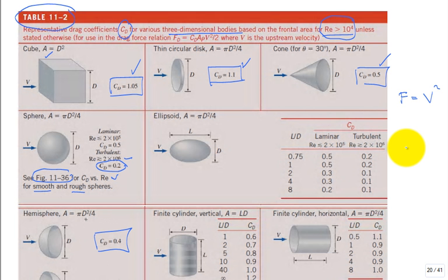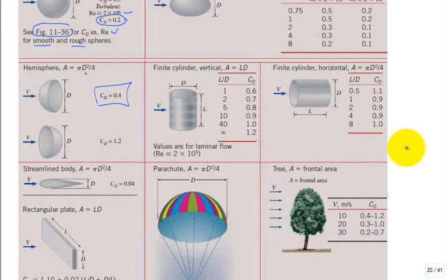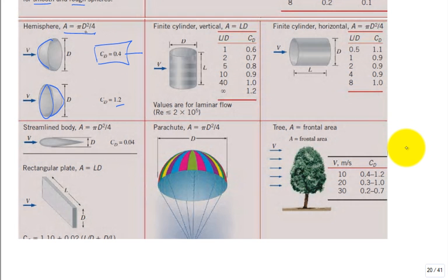You know, that cone has a lower drag coefficient, doesn't it? Even though it may have the same diameter. But the front area is going to help split the flow. So that's why the drag coefficient drops. Here's an interesting one right down here. A hemisphere, true? So this would be a solid, and in that solid, either the front helps split it, drag coefficient 0.4, or it's like a flat disc with a little on the back side, 1.2. Take a look also at, I truncated it, sorry, the parachute. The parachute lets air go inside and then kind of pushes it around. Maybe that doesn't show up so well, the color.